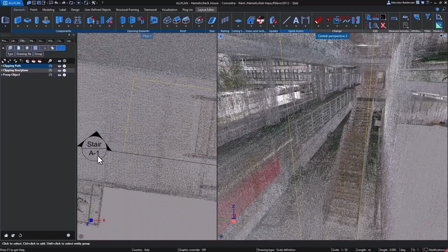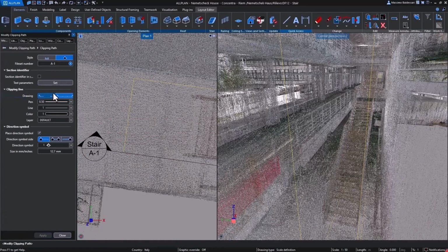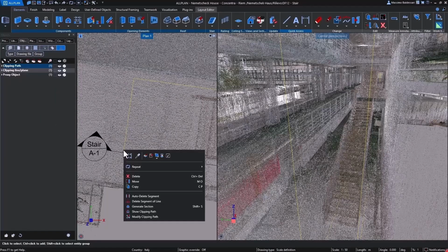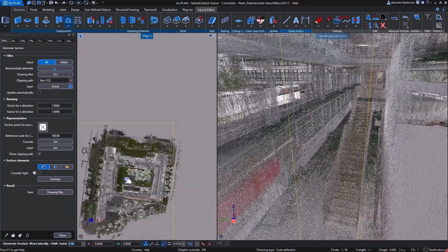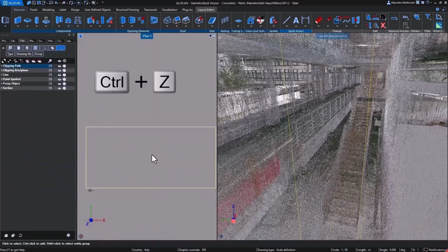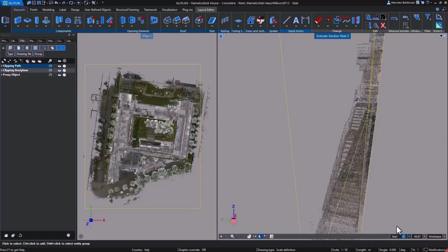So for step one, I created a classic section without extracting it yet. Or rather, if I were to go and try to extract this specific type of section, what happens? Well, what happens is that I simply don't get any kind of result at all. Now, why is that? Because the proxy object is an extremely lightweight object. Let's say it's not actually a real entity, and so it cannot be represented directly within my point cloud.